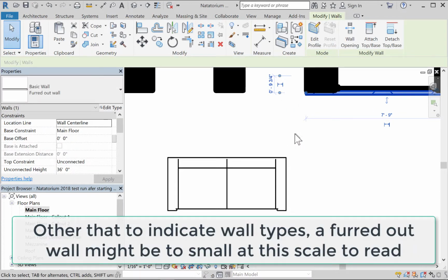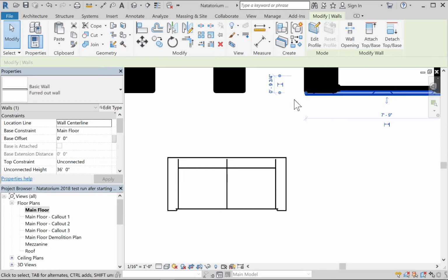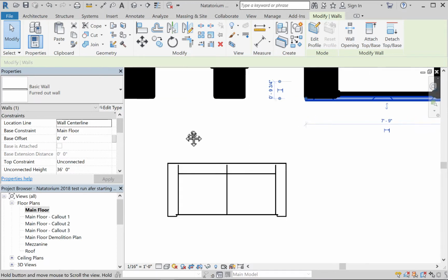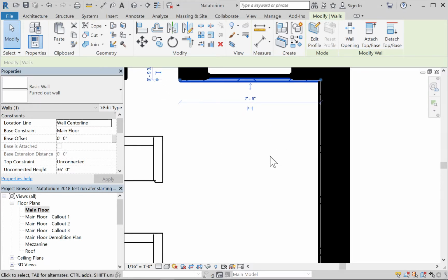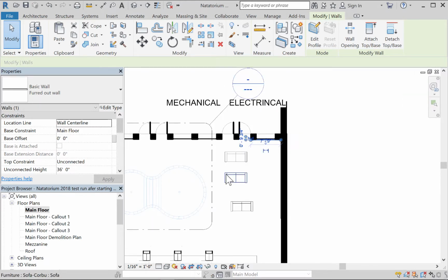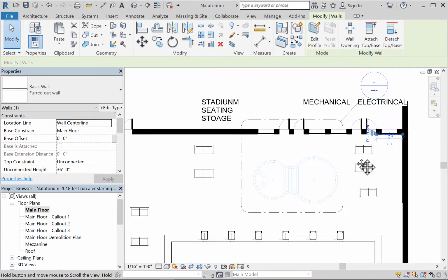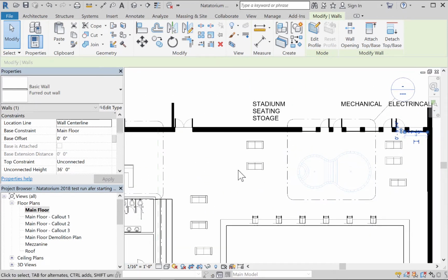And because of our interior elevations, we can just tell it not to show the finish here. That thin finish of 2 1/4 inch is not going to make a huge difference unless you have somewhere where it's tiling. But anyway, what this does provide us is an opportunity for the next piece, which is that every wall type you have needs to have a wall tag.